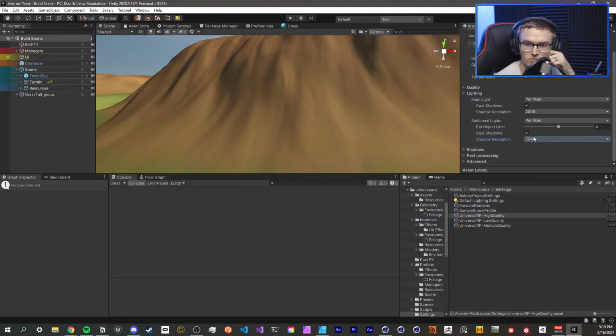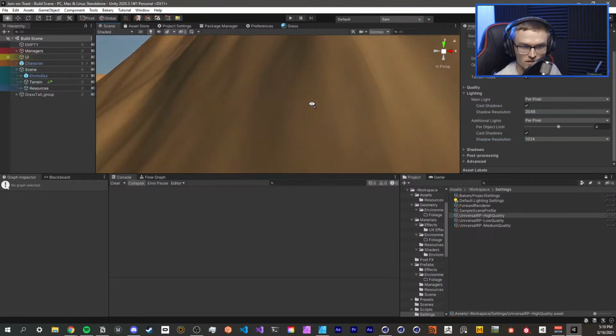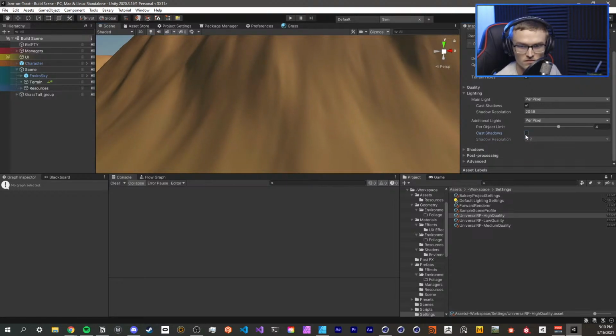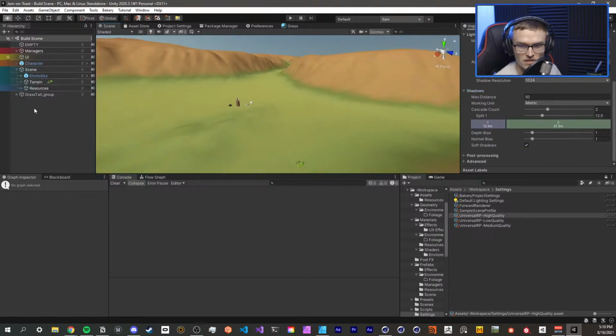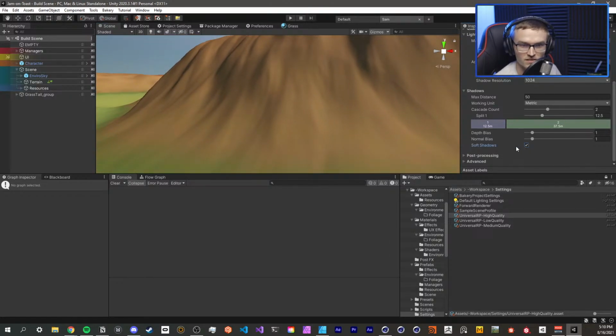Let's do 2048. That might be... Let's do 1024. That'll be a little bit better. Okay, shadow resolution. Yeah. Oh, that's what I was thinking. Okay. Yeah. Okay. Not sure what I did, but that's a lot better. I think it was just this. Okay. Well, the banding's not nearly as intense. Oh, it's soft shadows. That's what it is.